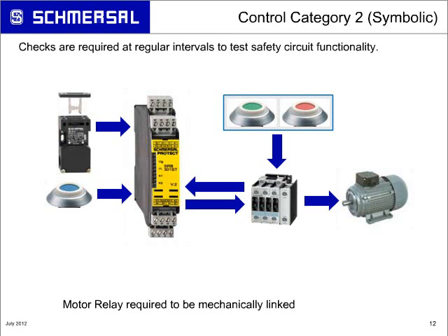Now, typically you hear a couple different terms: mechanically linked, positively guided relays, force-guided relays, mirrored contacts. They're all terminology that is resulting in meeting the same thing as far as a relay or contactor being allowed to use as a safety circuit or safety function. By standard, when you have a normally open contact that welds, the normally closed has to maintain a 0.5 millimeter gap tolerance from closing again.